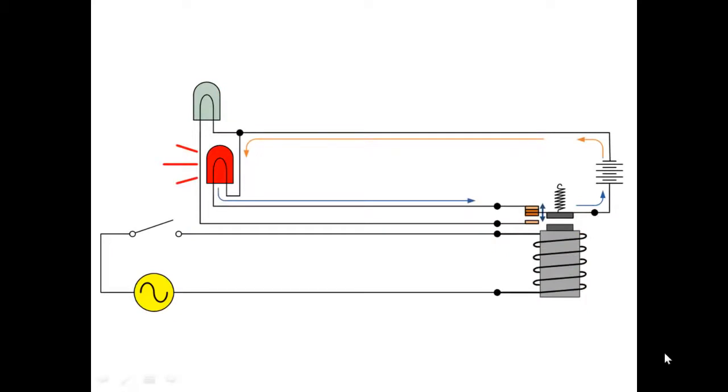This is an illustration of an electrical circuit, not an actual conventional circuit diagram. You would not see documentation on a control circuit that was drawn in this fashion. We've laid this out so it's easy to see the relationship of the power sources, the switches, the coil, the contacts, and the loads. In this case, the loads are the two indicators, the red and green indicator.